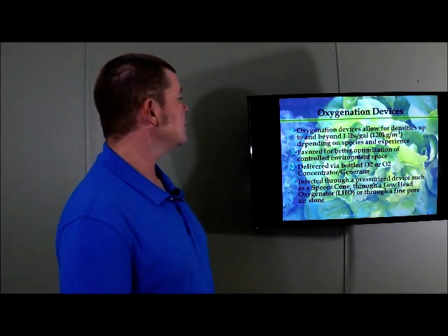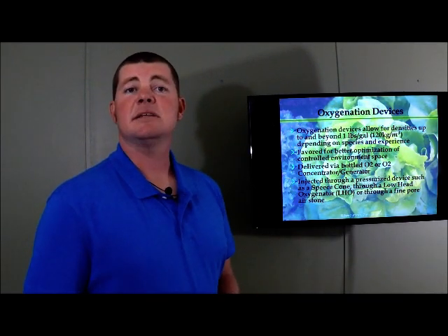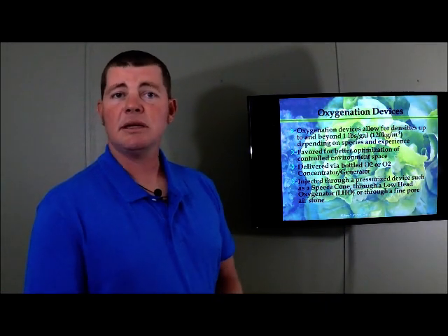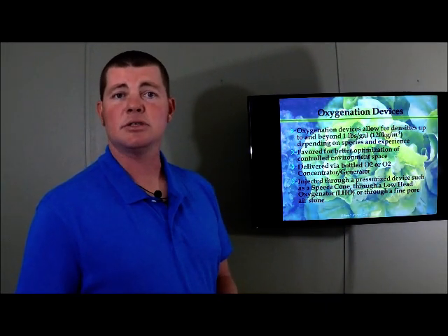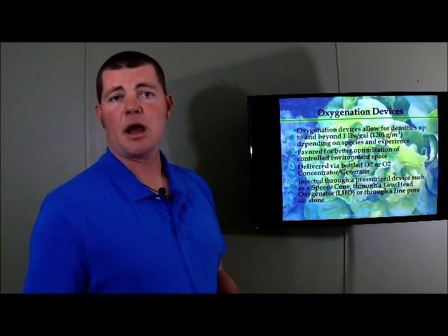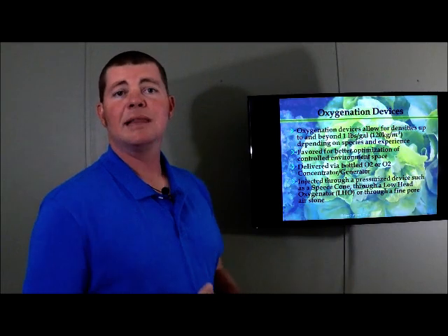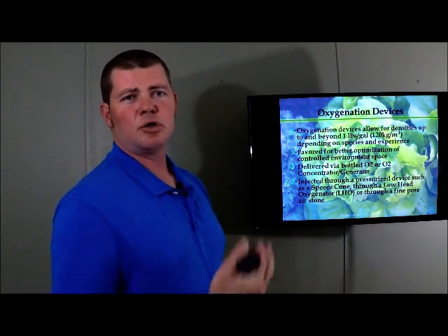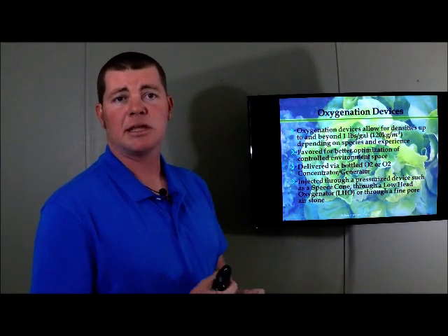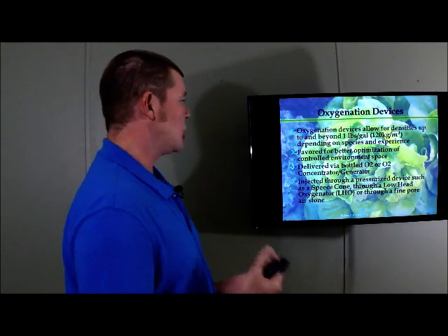An oxygen generator is actually a device that generates oxygen on site. Typically, in my experience, 92 to 96% oxygen. You'll get a higher percentage of oxygen from an oxygen bottling plant using liquid oxygen, which you'll hear me mention as LOX. That's liquid oxygen. It's the term for that.